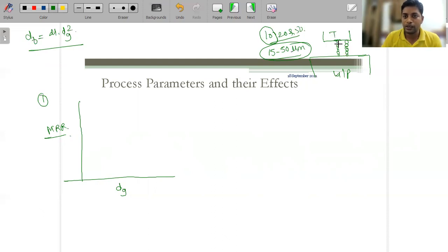But just suppose that this 15 micron is transferred to this one, it is in contact with the second one, third, fourth, fifth, sixth, seventh, like that. So they will reduce the amplitude which is really required at the workpiece surface. So what we are doing is increasing the size of the particles, and now this amplitude has increased.